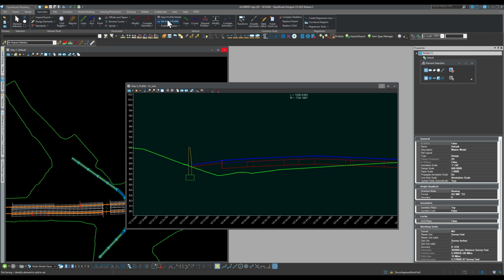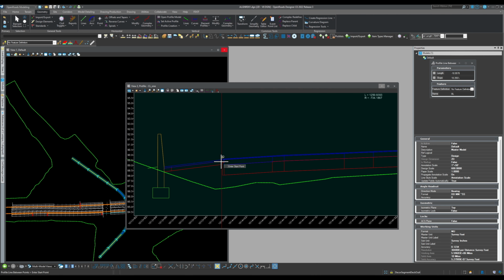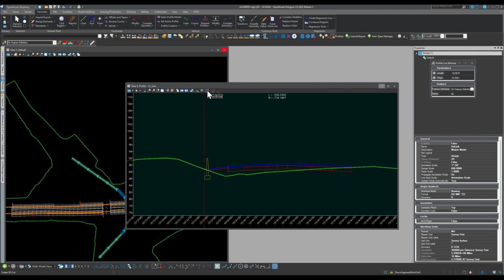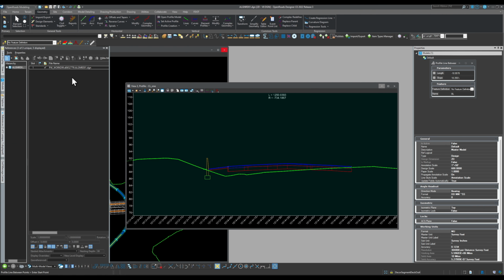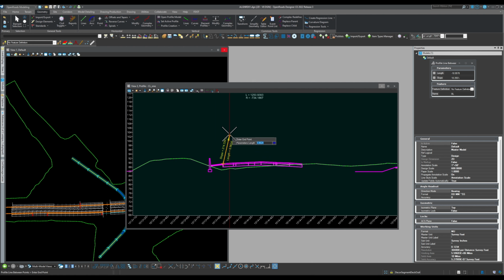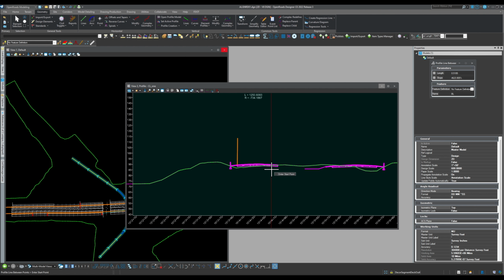So now we're going to do profile. We're just going to use the vertical tools. If I click here, as you can see, I'm trying to snap to these. I can't. By default, when you do a 3D cut corner, Bentley has them off. So you need to come here and then allow the snap. So now that I allow the snap, see what's going to happen. I can touch it, raise a line, do whatever, right?